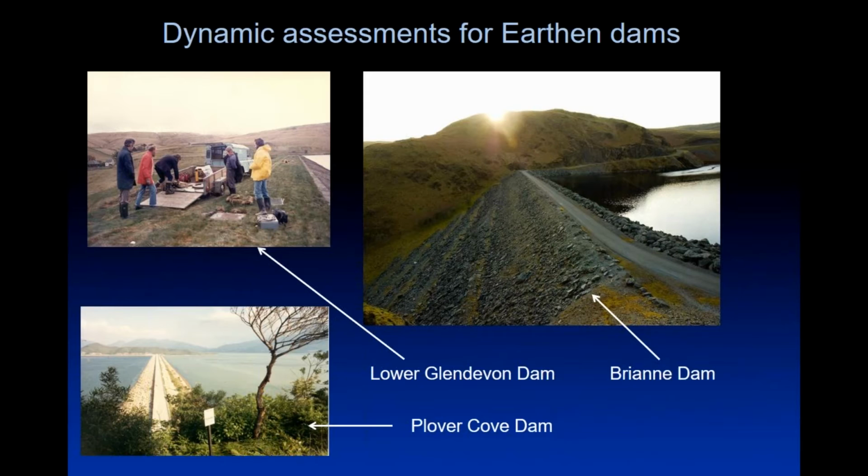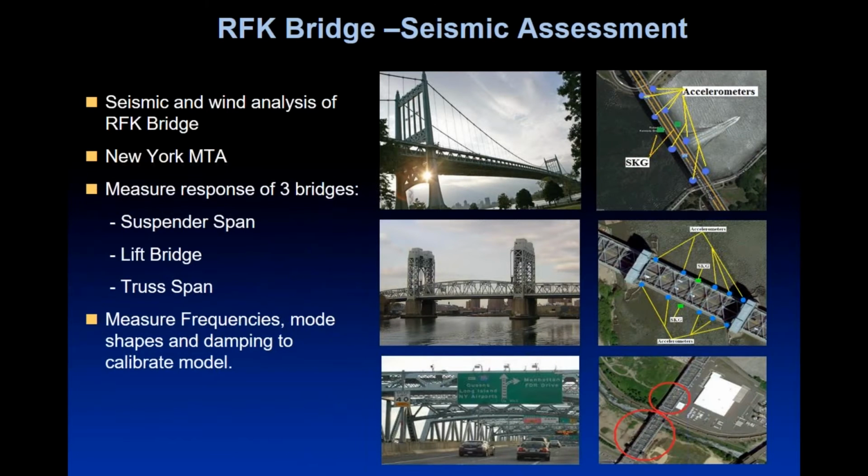As a matter of fact, normal all the way around the world is the same. It might be that the design makes designers do something slightly different, but the normal deflected form of the structure is really very well defined and can be retrieved from the response to random excitation, such as wind, wave, traffic, or earthquake, of course.